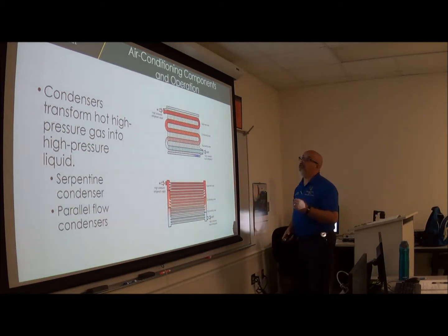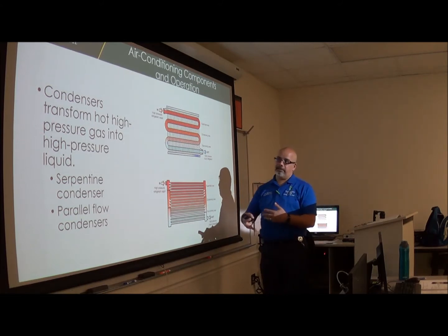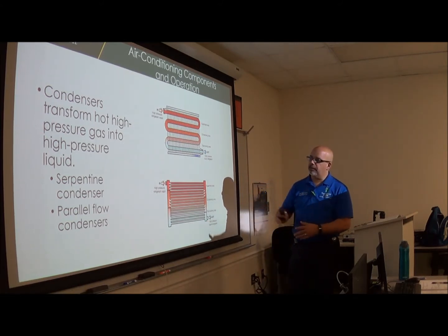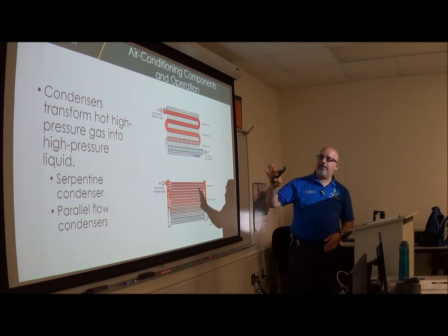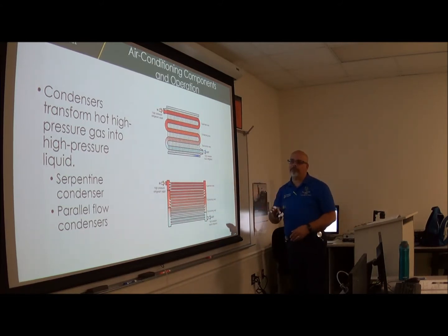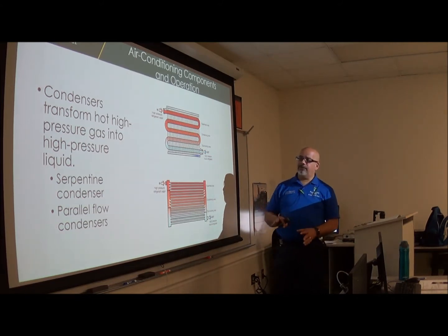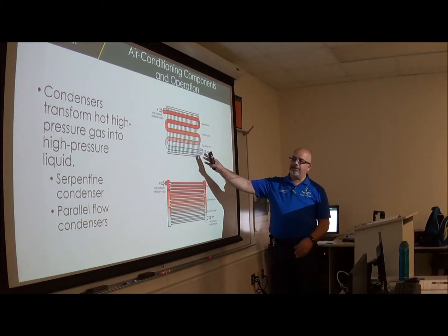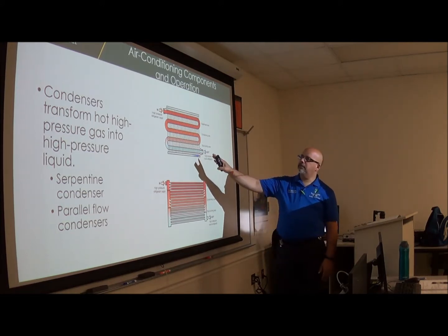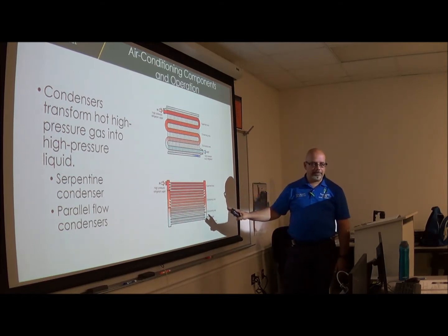Okay, so when we talk about condensers, the condenser, like I kind of explained a little bit in the first picture that I showed, transforms the high pressure gas into high pressure liquid. Okay? And we have two types of condensers. We have the serpentine condenser type, and then the parallel flow condenser type.